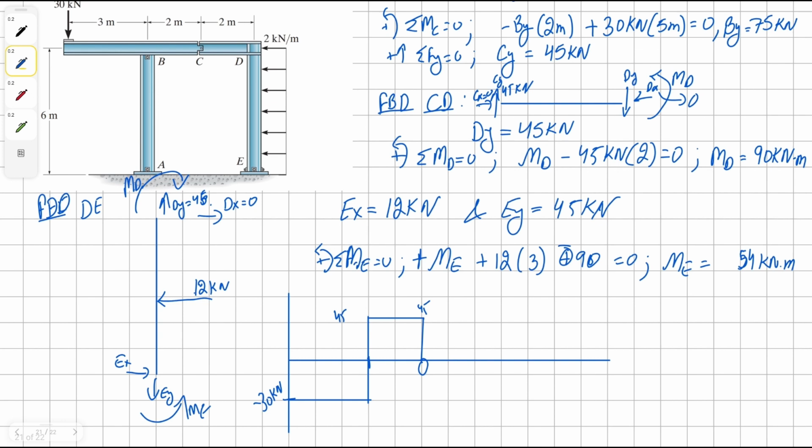Actually, we can have it as I've drawn it, or to make our life easier and not be drawing more individual shear moment diagrams, what I'm going to do is combine CD in this diagram as well. We're going to continue for 2 more meters and then come down to 0 with the bump from DY instead of the CY.